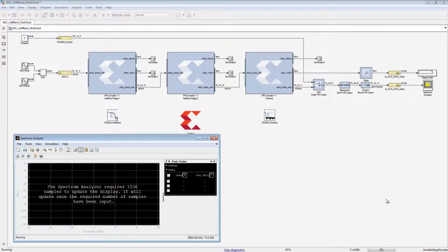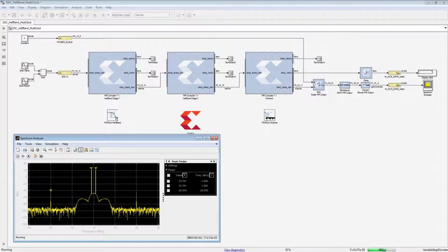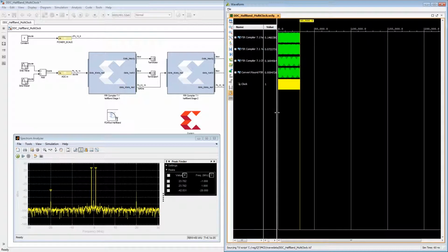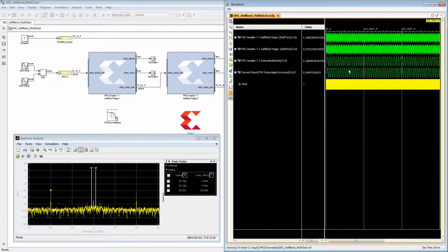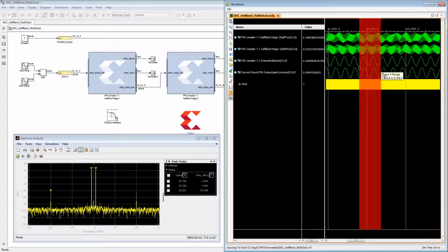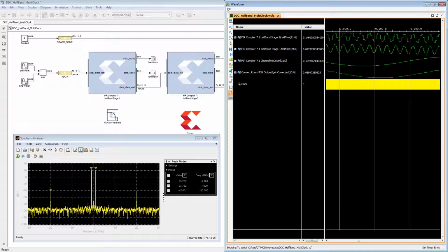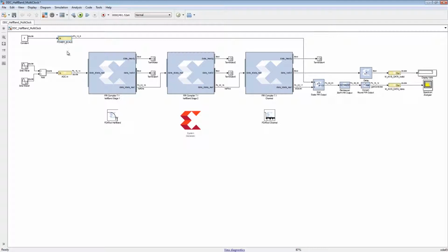This simulation demonstrates each stage's output data and final spectrum. This design uses 13 DSP slices instead of 128 for the single by 8 version. And we're taking advantage of the AXI streaming ports on the FIR compiler to easily connect multiple stages of FIR. We will abstract the handshake capabilities inherent in the AXI protocol through the automatic rate propagation delivered with System Generator. The FIR output is gain controlled through the PowerScale processor register, as shown in the previous Quick Take video, specifying AXI4-Lite interfaces for your Vivado System Generator design.